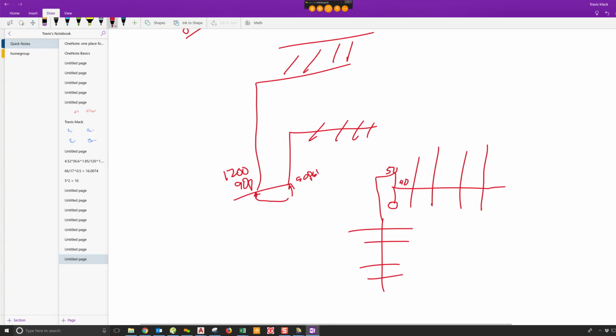All I did was I saw these two things. I said, well, hell, let's scrunch this down. Let's shrink this from his 3 to 2.5. Made these two pressures equal. Nothing over discharge, everything worked. So making pipe smaller actually made his system work when he couldn't make it work with 8-inch pipe.